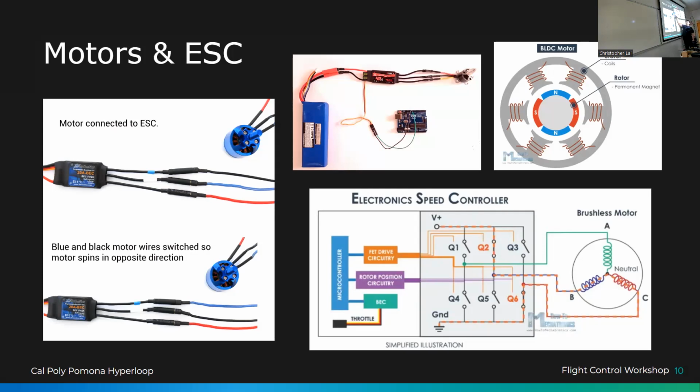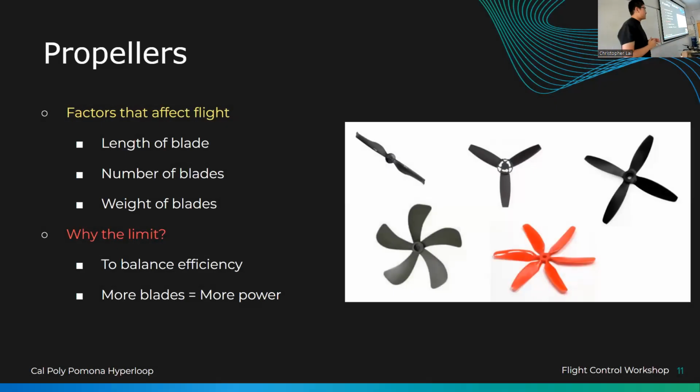And a LiPo battery, a big LiPo battery pack, is connected to the ESC, and the ESC takes the main power and the signal and uses them to control the motor. That's the control diagram right there. That's the easiest part of that slide, by the way. But you'll notice that drones have four of them.